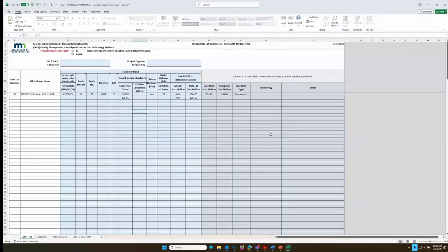Alternatively, you can just split the road, and what I've done a few times is, once you split the road, if you're just using the GPS to do that, right? Because now you're creating that alignment. Or even if you just split the road and take those offset stakes, shoot those and then offset into the center, whatever you're measuring, right? That works too. So a couple different ways to gather that information.